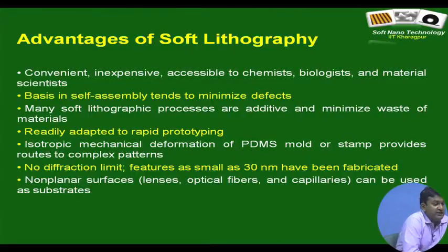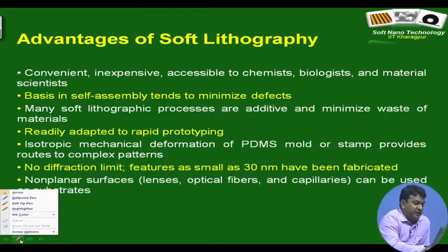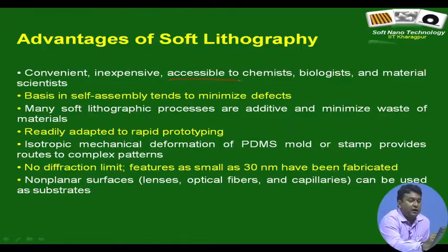So, it is convenient, inexpensive, it is accessible to non-experts. That is the most important thing. You do not need to be a real expert in patterning to perform soft lithography. It might be very likely that you are a material scientist, you need some pattern surfaces, or you are a fluid mechanics specialist, you need some pattern surfaces to study behavior of a fluid on a hydrophobic surface. And in your lab with minimal facility, you can in fact create structures or templates that is necessary for you. That is one of the biggest advantages.